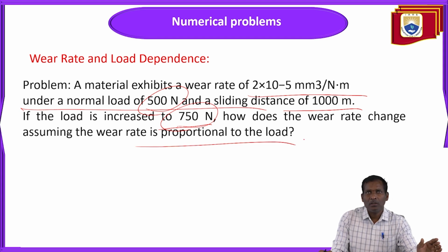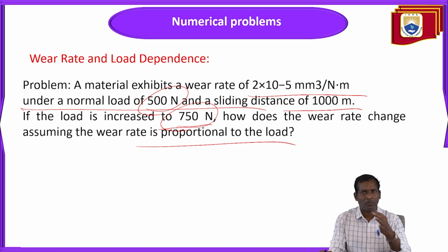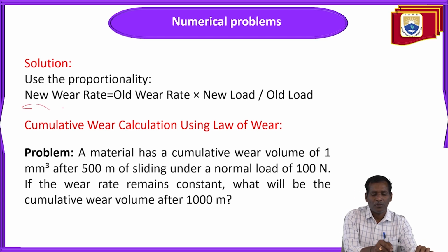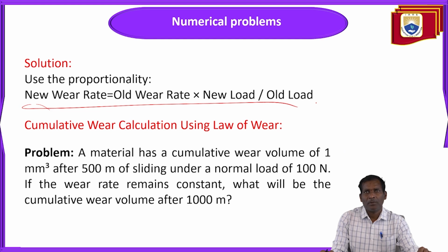So the solution is to use the proportionality. The new wear rate is equal to old wear rate multiplied with new load by old load.